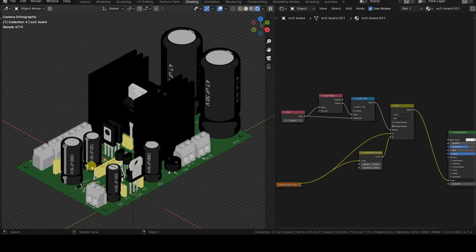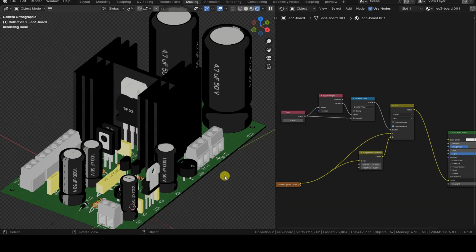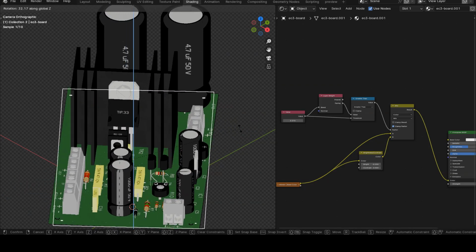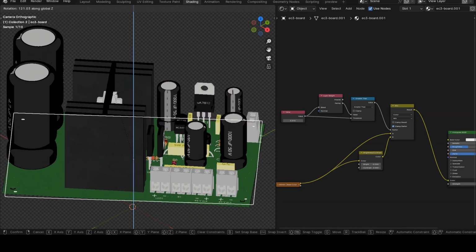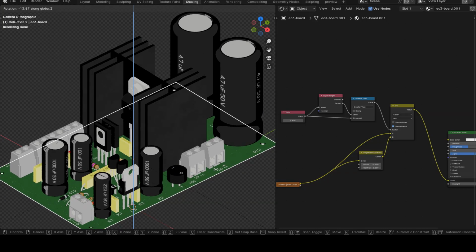The new shading has both positive and negative aspects. The positive aspect is that, thanks to Freestyle and the Facing node, the objects are no longer too flat, making it easier to perceive their volumes. The negative aspect is that this shading changes significantly based on the orientation of the objects relative to the camera, so it may be necessary to spend some time adjusting the Value node or the orientation of the objects.